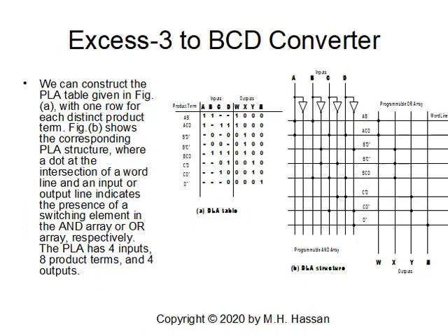Often, actually, those PLAs are much larger than the problem at hand, and you can implement the problem at hand very easily on a PLA. So this is the concept of how a PLA is used. So the PLA, again, has a programmable AND array and a programmable OR array. Unlike the ROM, where only the OR array was programmable, the AND array was fixed. We generate all the minterms, and the function was represented in canonical standard form as a sum of minterms.